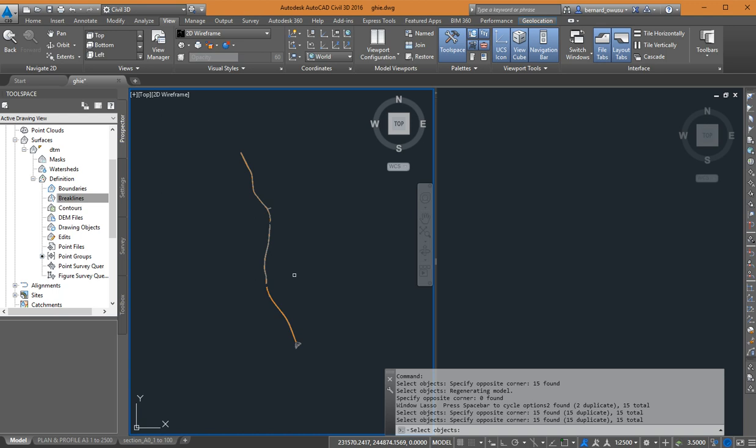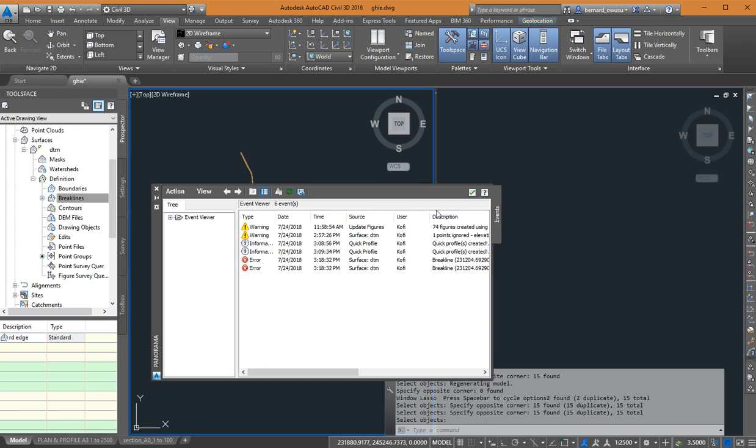So you don't have one. Go to break lines. Right click on break lines. Add. Put your name there. Okay, let's do it again. Then come and click on OK. Then come and draw a window around it. Then right click. So please, if you have finished, just right click and tell me what happens.